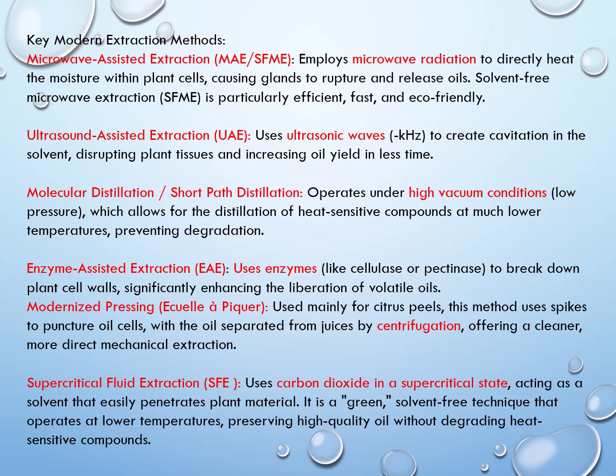Molecular distillation or short path distillation. This distillation operates under high vacuum conditions and also low pressure, which allows the distillation of heat sensitive compounds at a much lower temperature, preventing the degradation. So we can isolate the volatile oil without any degradation of active constituents.